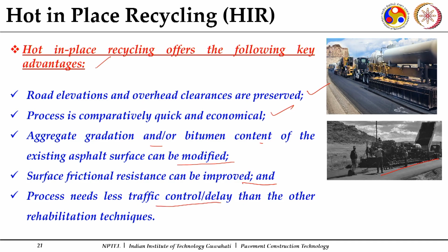And since this is done at the site itself, there is no bringing of mix, no transferring of material to the hot mix plants, and then bringing the recycled mix back to the site. So all these activities are not involved, and that's why hot in place recycling has fewer traffic control requirements and delays. But yes, this is restricted to the top 1 to 2 inches of distresses, where it can be very well done. So these are some of the recycling methods.